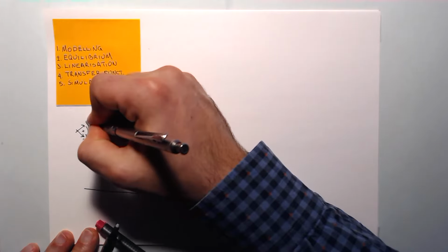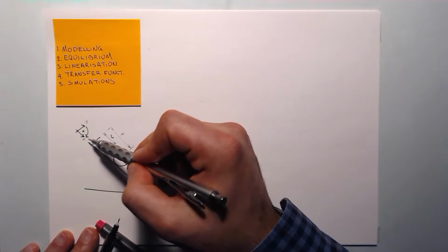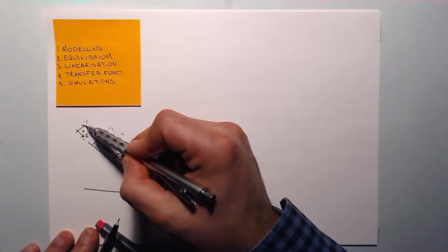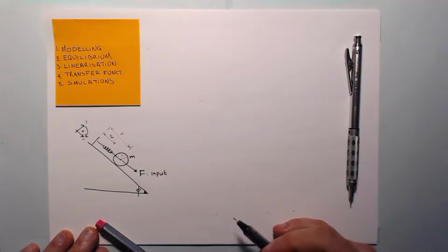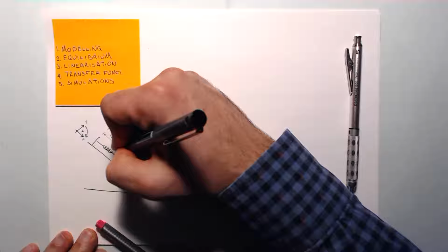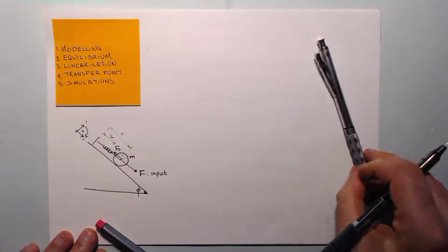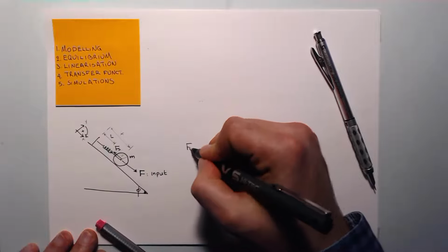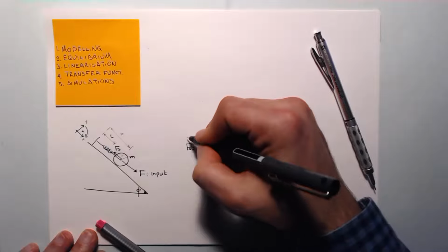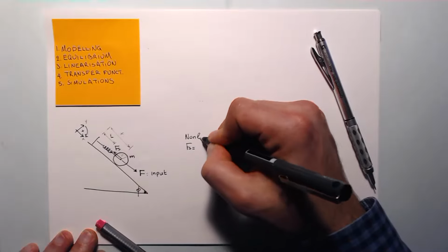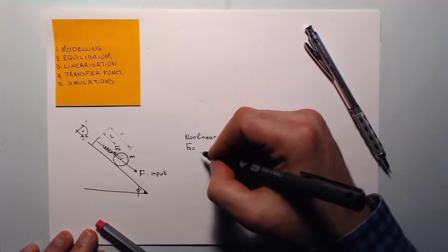This is the x-axis, this is the y-axis, these are the positive directions, and as you see here from the convention we're using, clockwise rotations are considered to be positive. Another force apparently is the restoring force Fs of the spring, and I'm going to tell you that Fs is given by this nonlinear equation. So we have a nonlinear spring, which is not governed by Hooke's law. It's not an elastic spring.